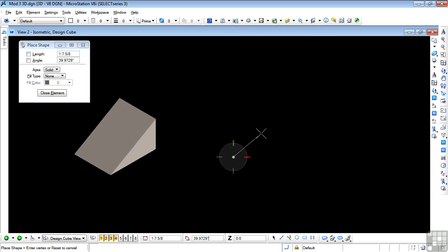The compass shows in view orientation, which I don't want, so I'm going to use E at the keyboard. That orientation, because I'm going up at 30 degrees in that direction. So now I enter my 30 degrees, so I will tab to the angle value in AccuDraw at the bottom of the screen, enter my 30 degrees, and data point. I'm not using any particular dimensions here.